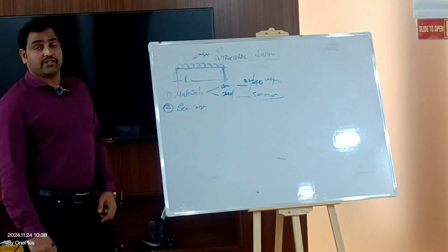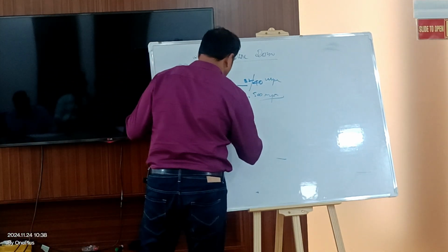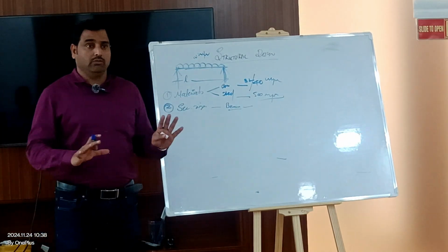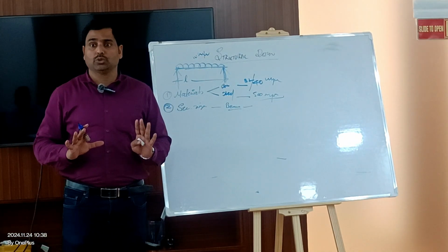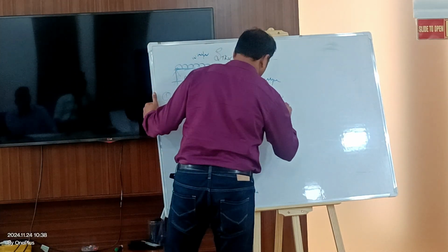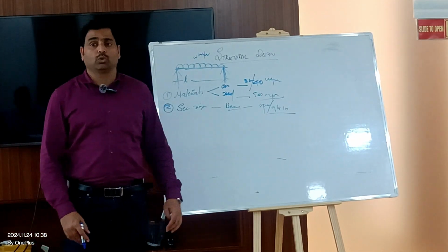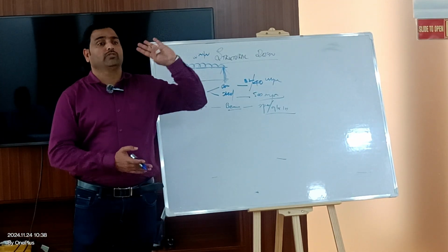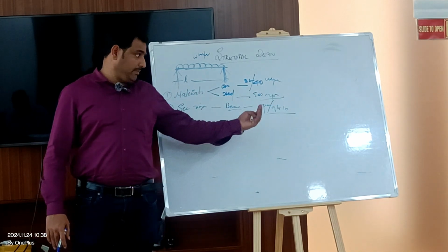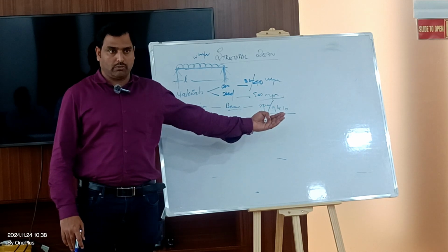The second is what? Section sizes, right? The moment you're talking about beams, very practical, we will not go as per code, because now you are going to do the real design. Span by 9 to 10. What is span by 9 to 10? To define the overall depth of the beam. You can go for span by 9 or span by 10. Span by 9 is a bit optimum, right? Span by 10 is a bit optimum, correct?